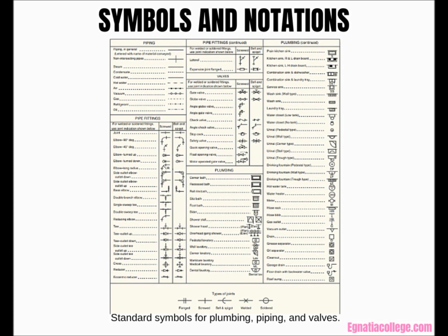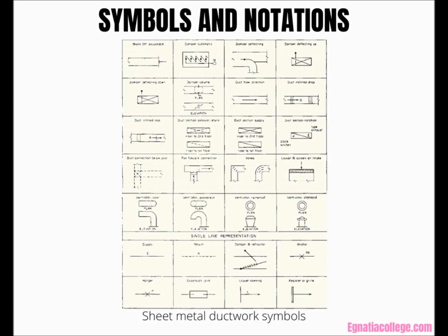The orientation of a symbol on a drawing does not alter the meaning of the symbol. Lighting fixtures are generally drawn in a manner that will indicate the size, shape, and orientation of the fixture. Symbols found on electrical plans indicate only the approximate location of electrical equipment. When exact locations are required, check the drawings for dimensions and confirm all measurements with the owner or owner's representative.